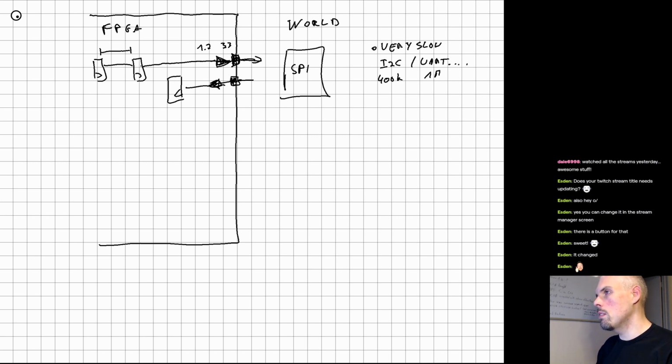I mean, if you do some asynchronous sampling, you might need a dual register in the FPGA to avoid metastability, but that's a distinct thing from I/O timing. That's something completely different, and that's outside the scope of what I'm talking about here.